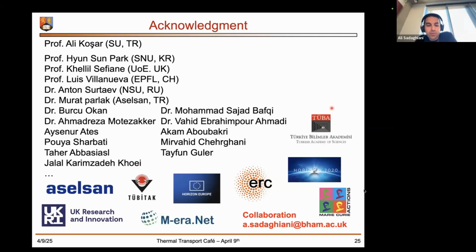Thank you. This is a great question, and I will answer it from a different perspective. For circular shapes, the optimum configuration is an interaction between the liquid film evaporation and the spots. If it were a hydrophobic spot rather than a superhydrophobic spot, we would definitely have a different A star value. And if we had a different background wettability rather than 30 degrees, we would again have a different A star value.